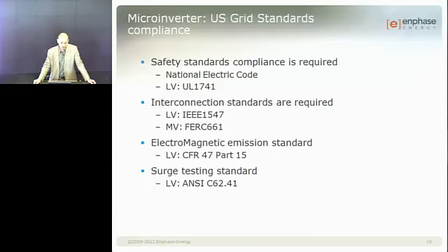So there is an IEEE standard called 1547, which says exactly how the inverter should respond to overvoltage, undervoltage, off-frequency behavior, and so on and so forth. That's for the low voltage side. On the medium voltage side, we will have to comply with the standard called FERC 661, which does a similar type of requirement at the medium voltage level.